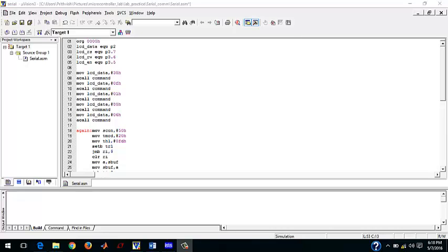character. So here you can see the basic commands of an LCD to initialize the LCD, to point it to the first character, and then clearing the LCD, cursor blinking, and for every character you print shift right, the basic commands that you use for LCD. Here comes the serial communication part.